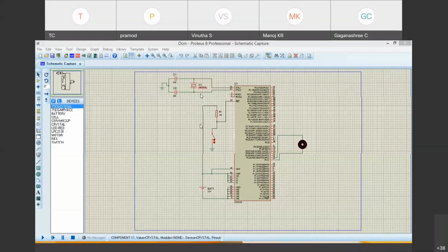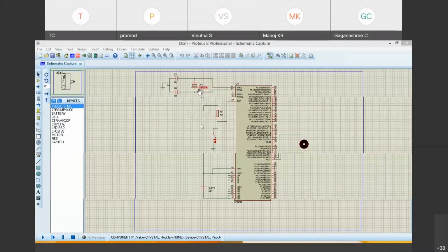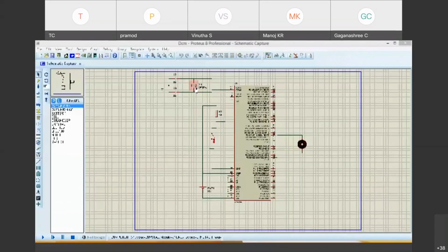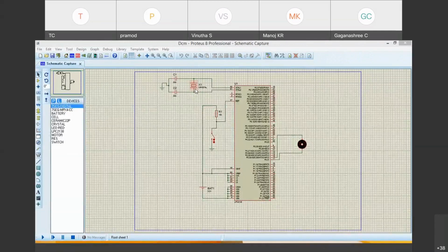You know how to connect them to ground. Ensure that the crystal you have chosen, when I double click on it, is set to 12 megahertz. Then take a resistor. That's what you see on the component side here: 7 segment digital.